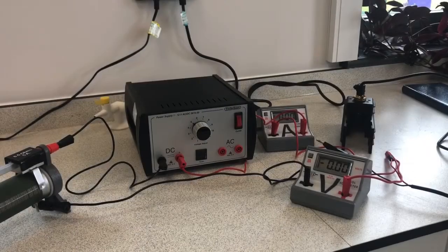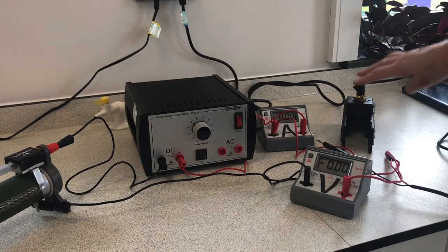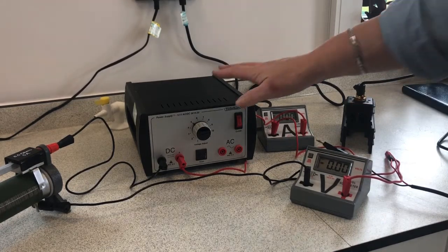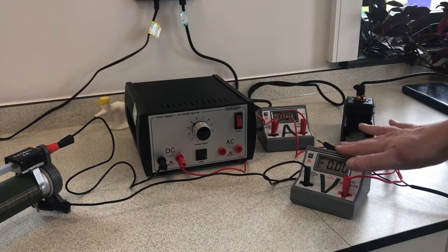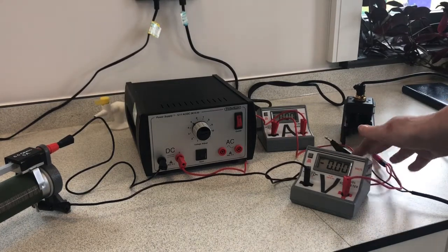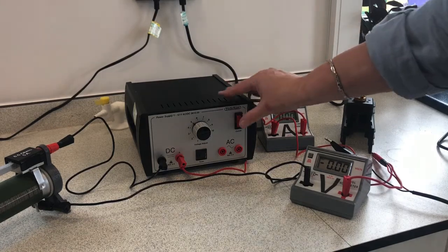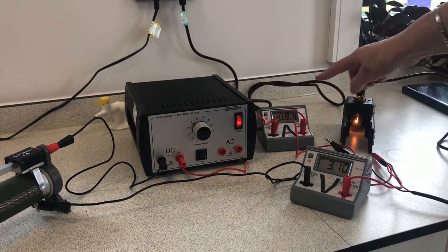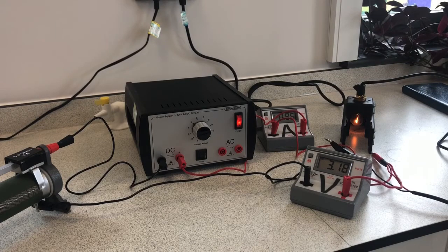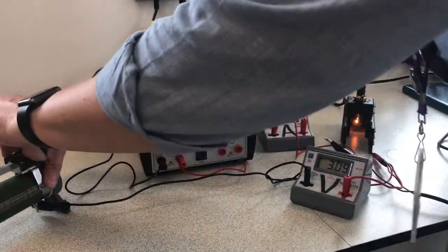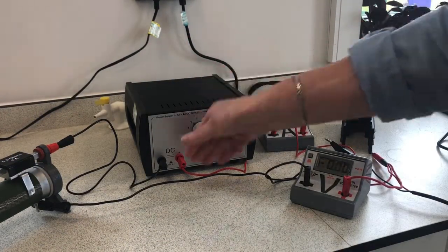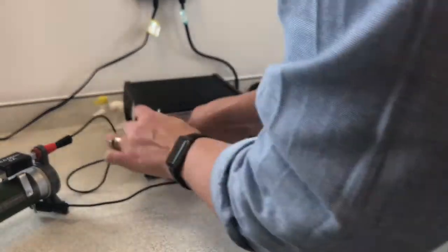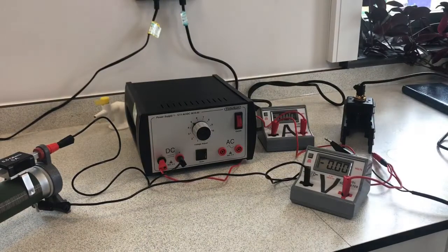So for the second part of this practical, we've just replaced the resistor with a filament lamp. So we've got the power supply, ammeter, lamp and variable resistor all set up in series, and the voltmeter in parallel over the filament lamp. So we're going to do exactly the same, turning on the power and taking our readings from the ammeter and from the voltmeter, altering the variable resistor and taking a range of results. We're then going to change the supply from positive to negative, so we change our direction and again take a series of results.